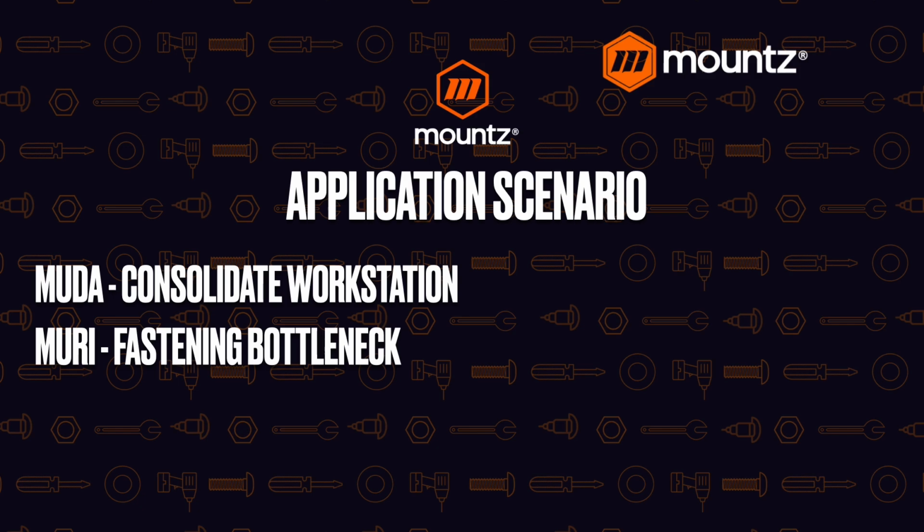And typically when we're dealing with lower torque values, RPM really plays a factor in how accurate we can be, especially at the low end, as we're dealing with trying to control inertia that may be happening when the tool shuts off, giving us some erratic readings.